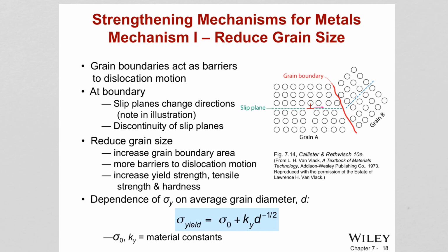All right, we are seeing the effect of grain size on the strengthening of metals. So we are seeing two different grains side by side in a polycrystalline material. There is the grain boundary, and there it goes, your dislocation moving, and it will try to pass from the boundary to another grain, right? And this will require more energy than it did when it was slipping before. So grain boundaries are barriers to dislocation motion.